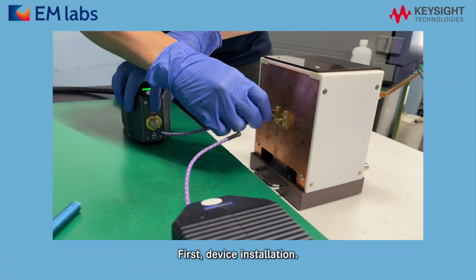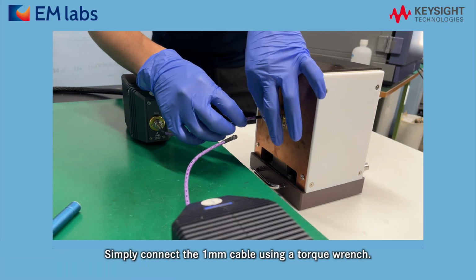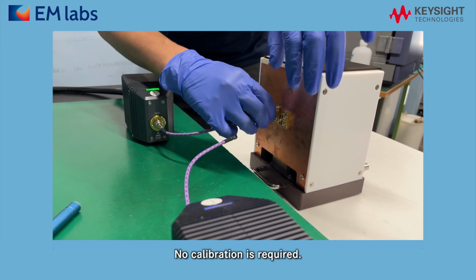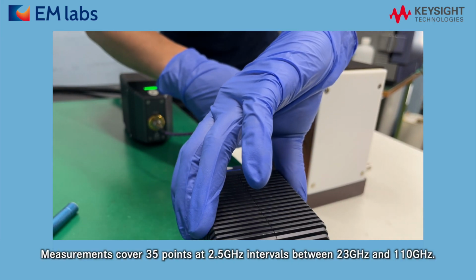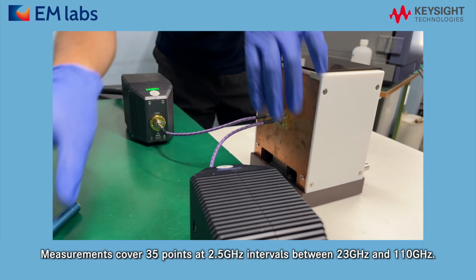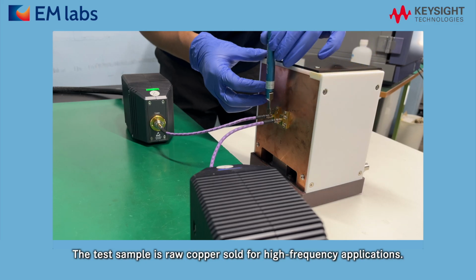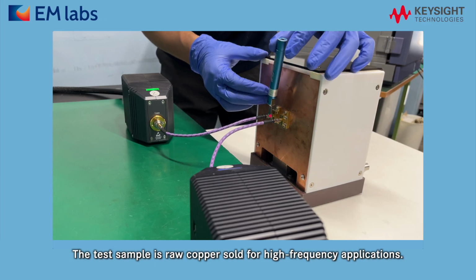First, let's install the device. Simply connect the 1 mm cable using a torque wrench. No calibration is required. The measurement covers 35 points at 2.5 GHz intervals between 23 and 110 GHz. The test sample used here is raw copper sold for high-frequency applications.